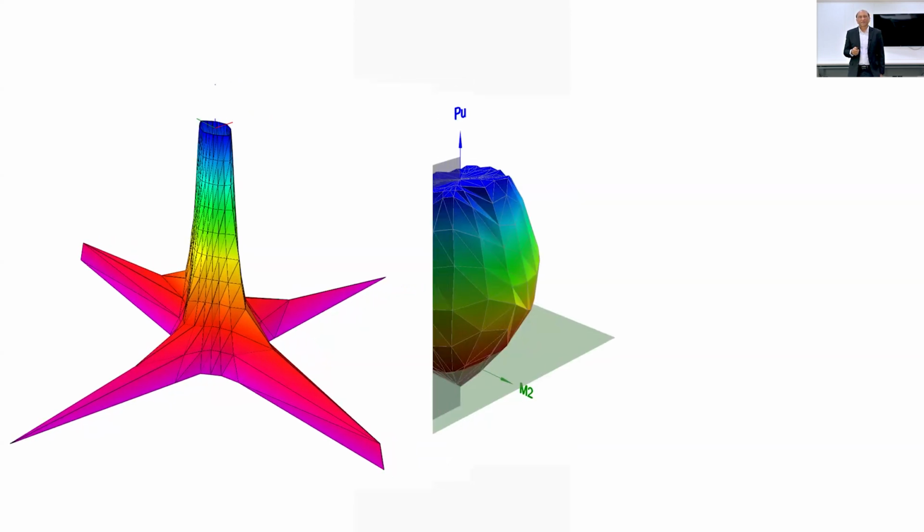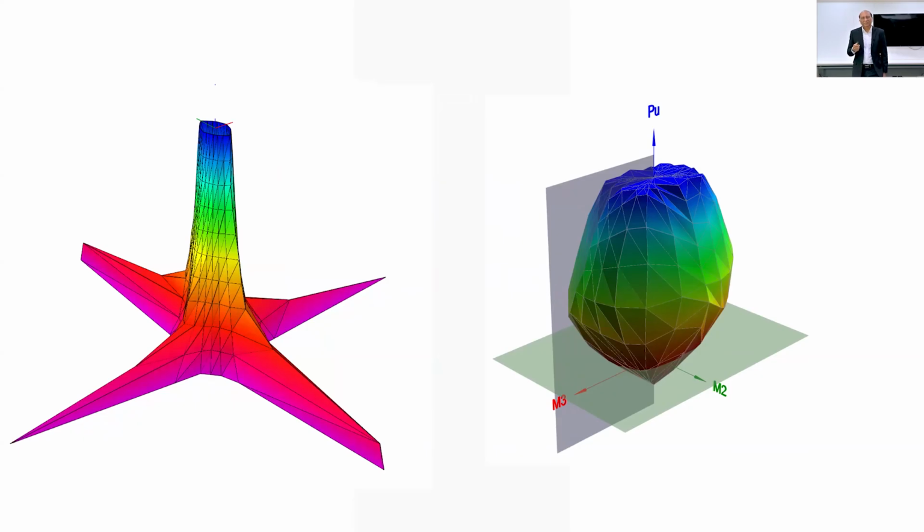So I mentioned earlier that axial load has a relationship with the moment curvature, because of equilibrium and because compressive load can consume most of the concrete capacity. So when your compressive load is increased, the curvature capacity reduces. So as you increase P, curvature capacity reduces. And this is a plot that you can see, and you can compare it with the PMM diagram.